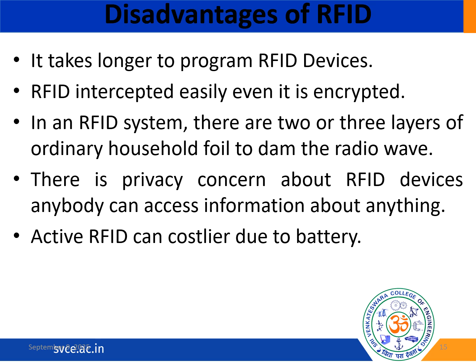So it can raise concerns about unauthorized access to sensitive information, and potential misuse of personal data. Active RFID can be costlier compared with passive RFID. Active RFID tags include built-in batteries for extended range and functionality, so they are comparatively costly and have a limited lifespan due to battery depletion.